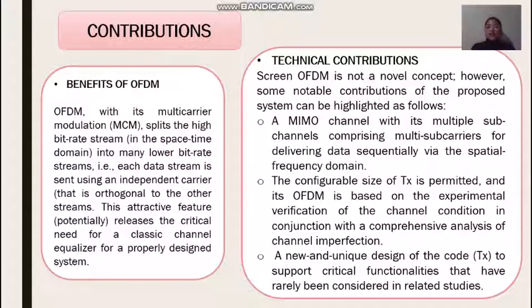The second point on the contribution is technical contributions. A screen OFDM is not a novel concept. However, some notable contributions of the proposed system can be highlighted as follows. First, a MIMO channel with its multiple subchannels comprises multiple subcarriers for delivering data sequentially via the frequency domain.